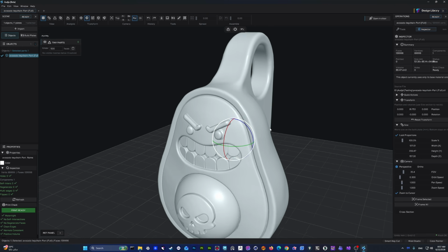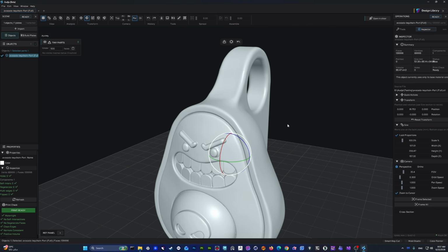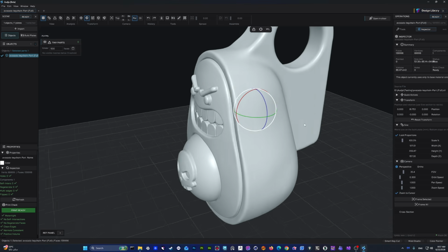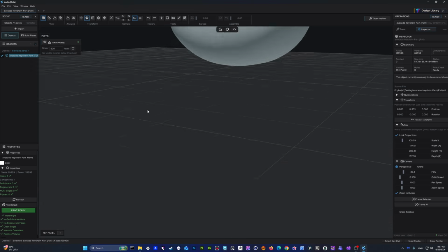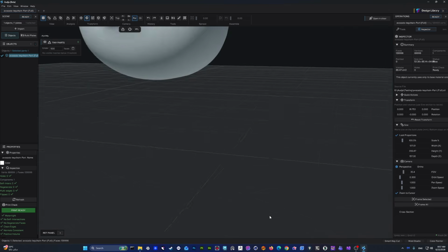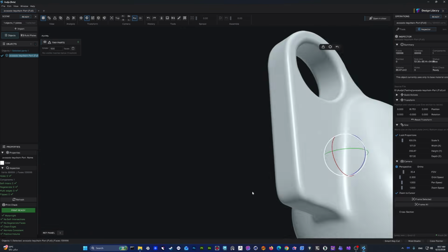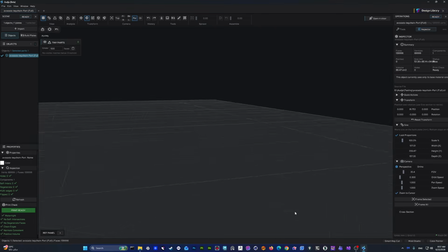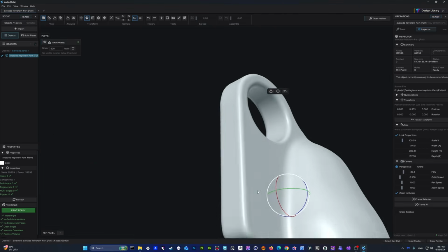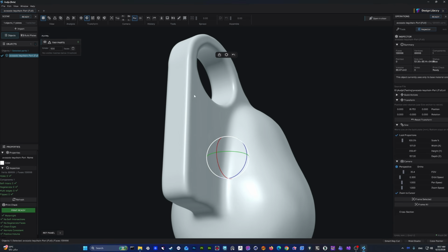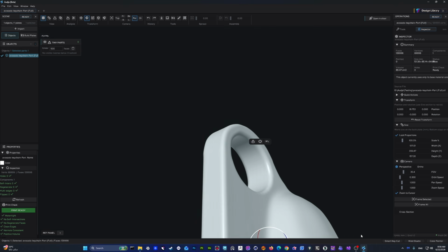And there is an important thing, it's about the orbit focus. So let's say you zoom in the space, and as you can see, I lost the orbit focus, so I can't rotate around the model. It is rotating in the space, and that's a big issue for me. So you can put the mouse on any part you want to focus on. So let's say I'm gonna put it up here, see, and I'm gonna press tab, see here, orbit focus.